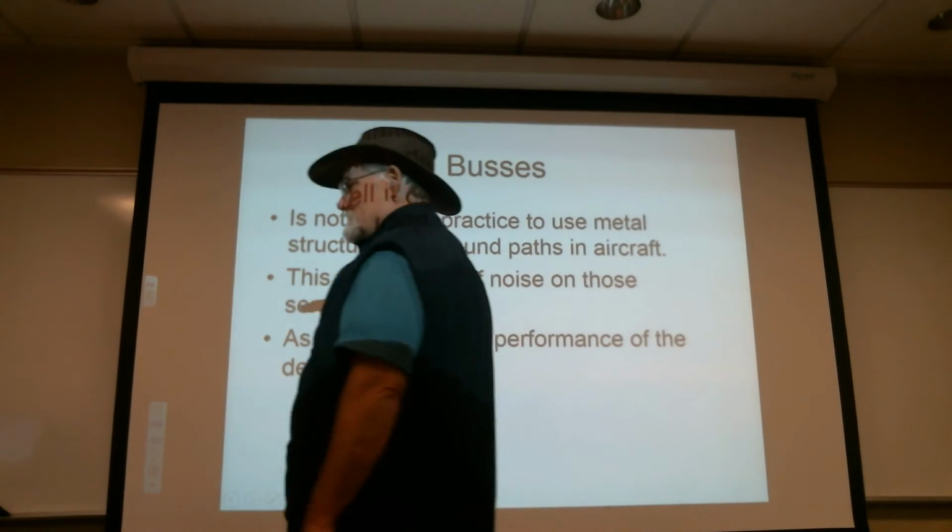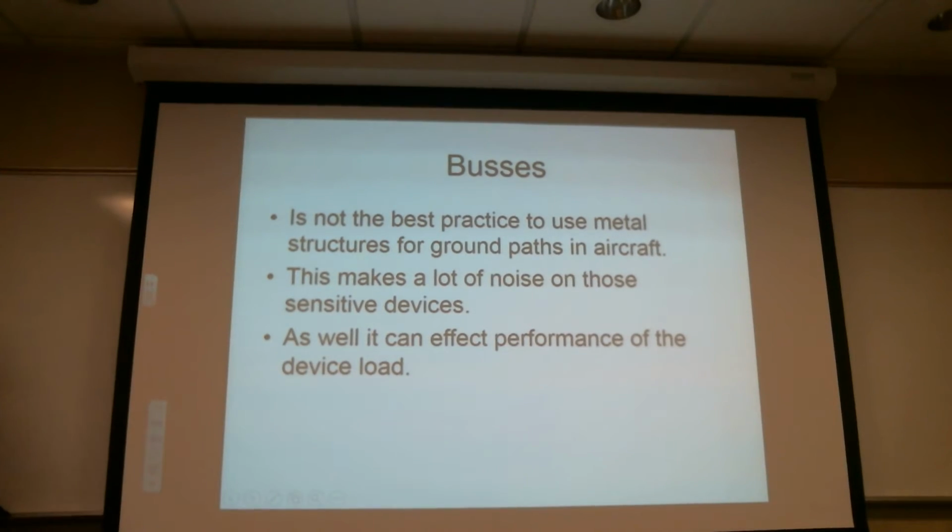Well, weren't most general aviation aircraft grounded through the frame? Very commonly they are. It is what it is. Again, if you start having really weird problems like that... but the other thing is, it doesn't necessarily have to go through an electronic component. It can go through a mechanical component. You can have a one-shot ground loop.